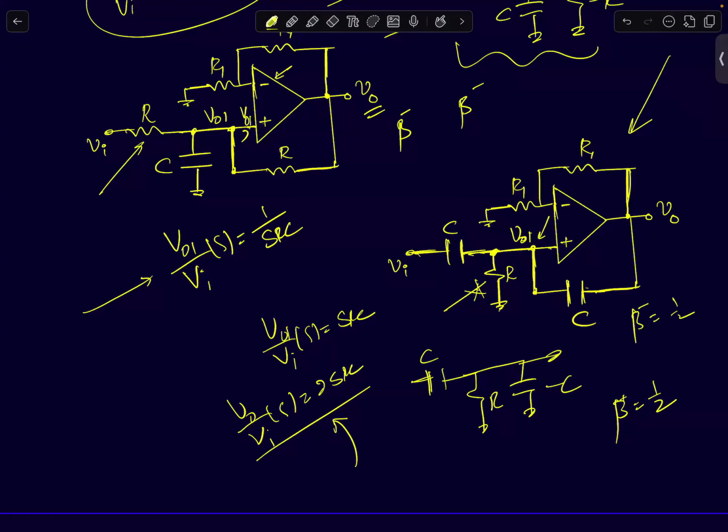That is also half because it's 2 resistors. So now this is a circuit where both these factors are equal. When both of them become equal, you can't precisely say what is the steady state operating point of the circuit. So anytime your output changes, both V plus and V minus are changing by the same amount. Therefore, we know no signal will be fed back. The net feedback will be 0 because beta plus is equal to beta minus.